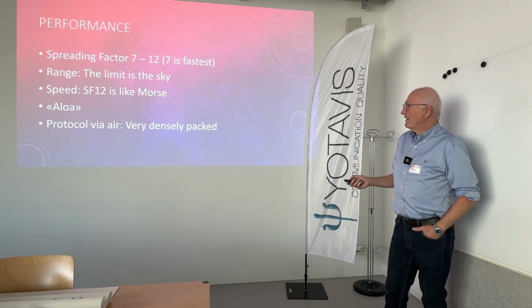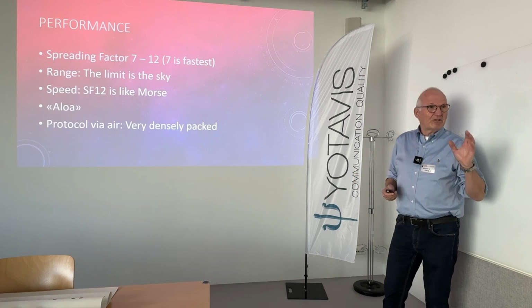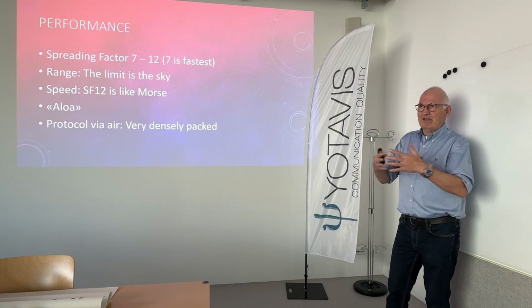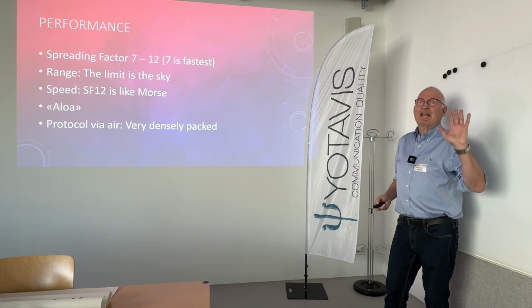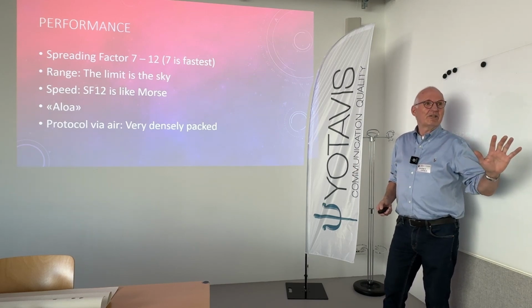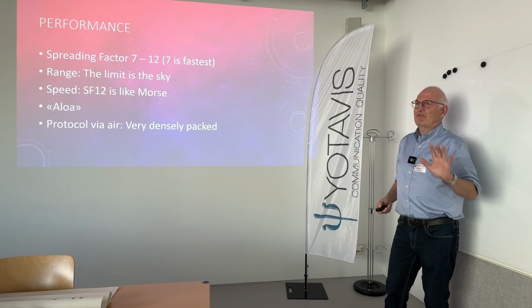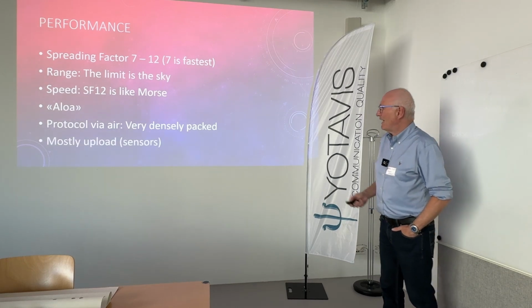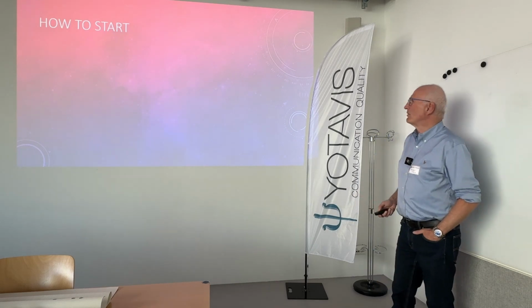So it is very, very important that you respect this, because otherwise others will not work on the same channel. We have 8 channels in Europe for LoRaWAN. They are all the same. And as I mentioned, it's mostly upload.